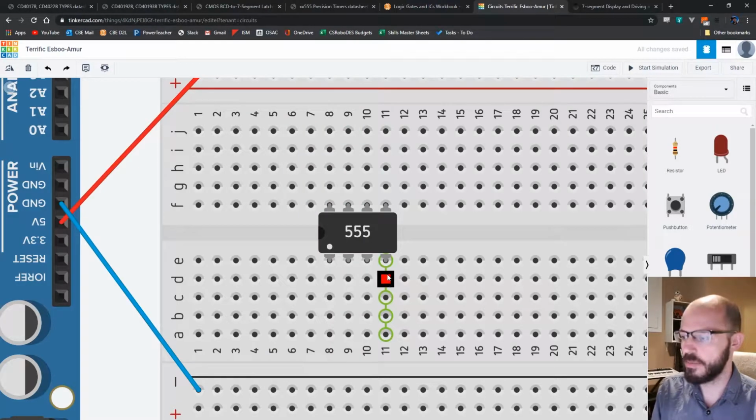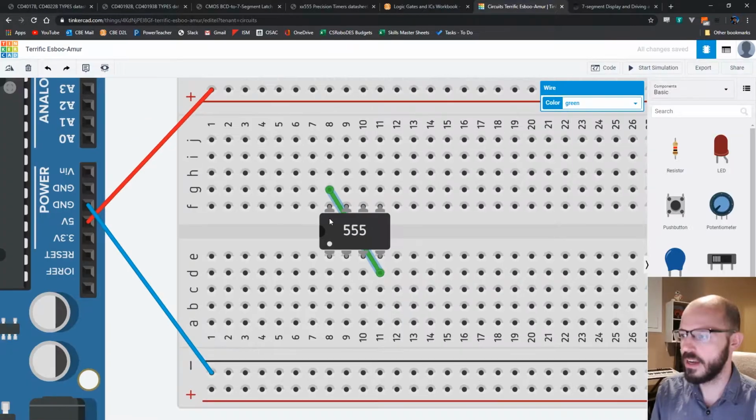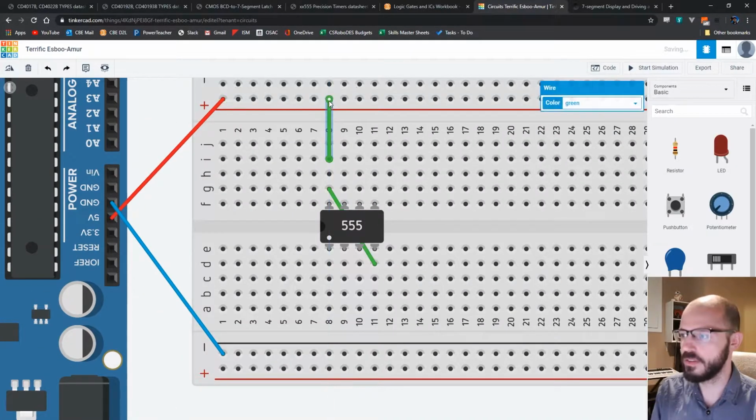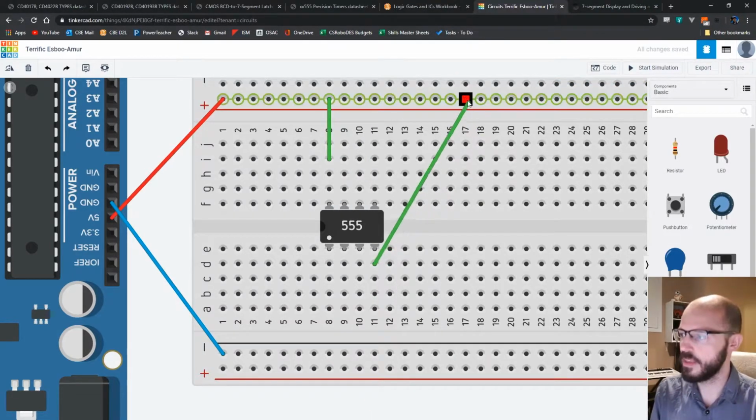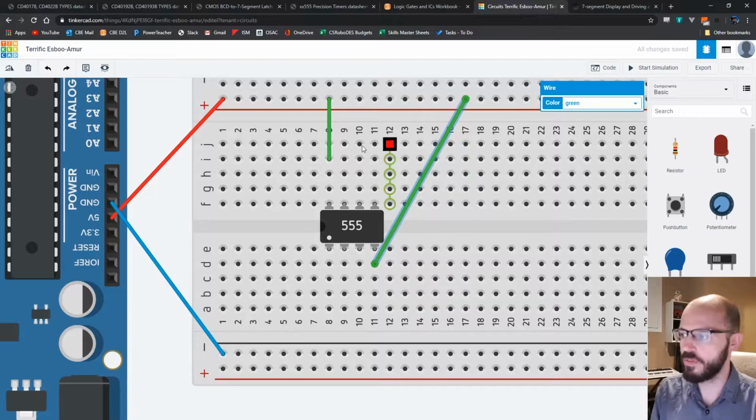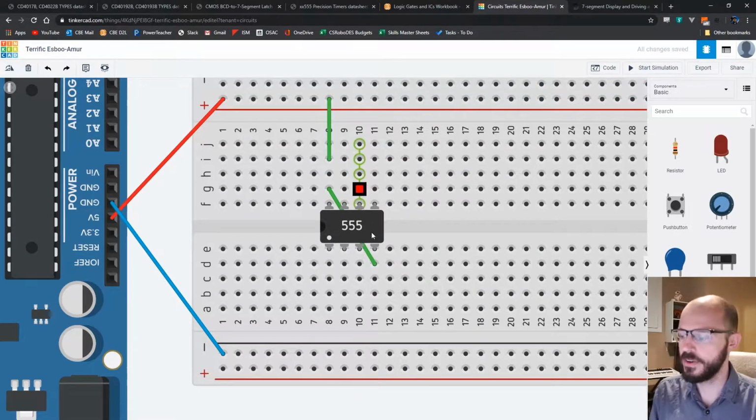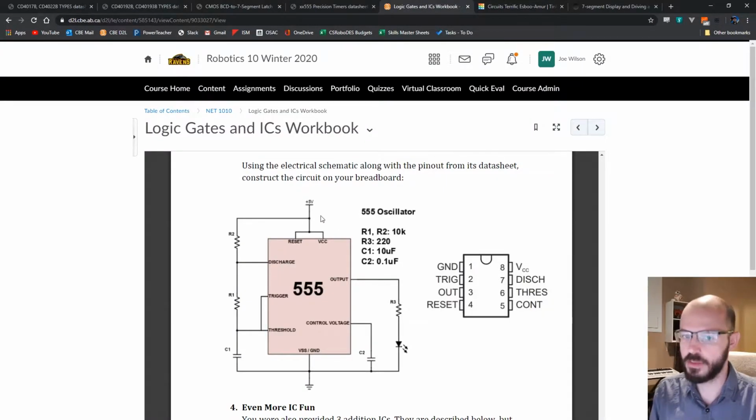By that circuit diagram, the schematic diagram, we could connect pin 4 to pin 8 and then pin 8 up to positive. This works. You could do the exact same thing, accomplish the same thing electrically by connecting pin 4 to 5 volts and pin 8 to 5 volts. Both work. Either way, it doesn't matter. I'm going to do this just because it's a little cleaner. So just a little jumper that's going to hop over my IC to connect 4 and 8 together. And I will color code these red to indicate that they're going up to 5 volts. So we've done this little segment here.